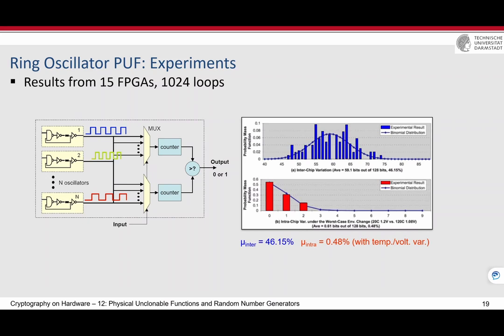Then for a certain period of time, for example 10 clock cycles of the general clock of the system, you count based on the clock which is given through the multiplexers. Then you stop after, for example, 10 clock cycles, and you check which one is larger than the other. The output is 0 if, for example, this one is larger, or else the other one. This is one way of building the PUF, and this is actually your assignment.